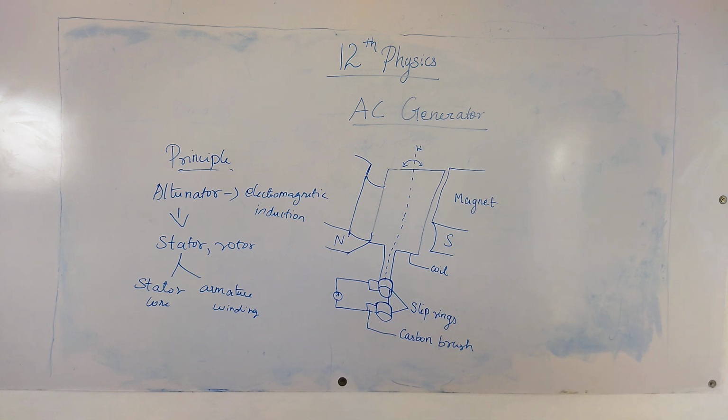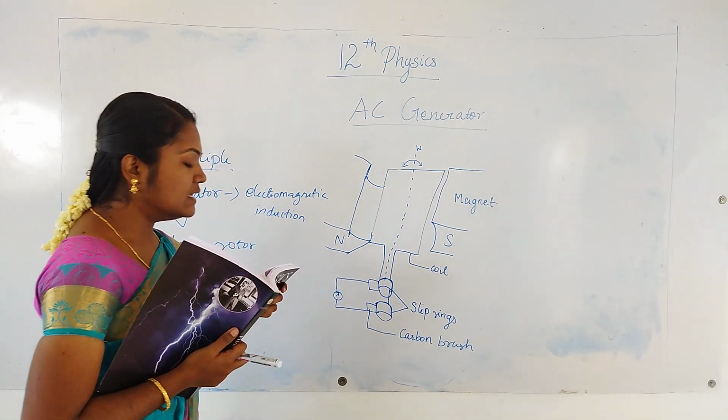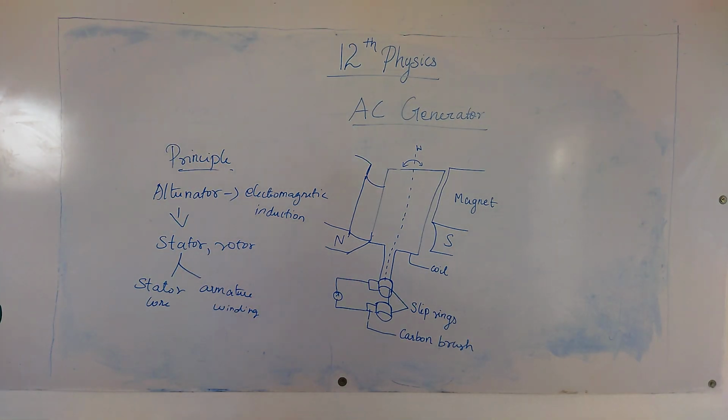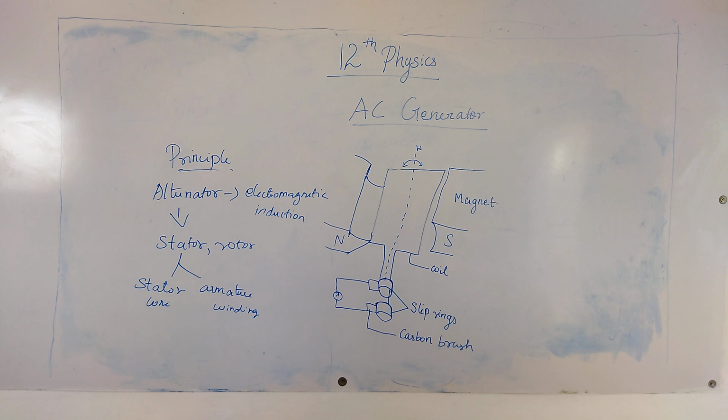The number of sliding contacts, that is slip rings, is reduced. Moreover, the sliding contacts are used only for low voltage. The armature winding can be constructed more rigidly to prevent deformation due to any mechanical stress. These are the advantages of the stationary armature rotating field alternator.